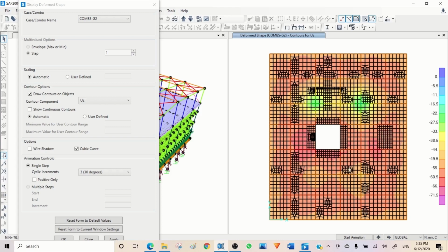But if you don't have, be a little bit conservative in deflection and ensure that the serviceability requirements can be met. So this is what I do, and if I have any transfer slab and I want to get the transfer loads, I need to increase the stiffness sometimes locally to ensure that the deflections are matched with the type of slab I have.